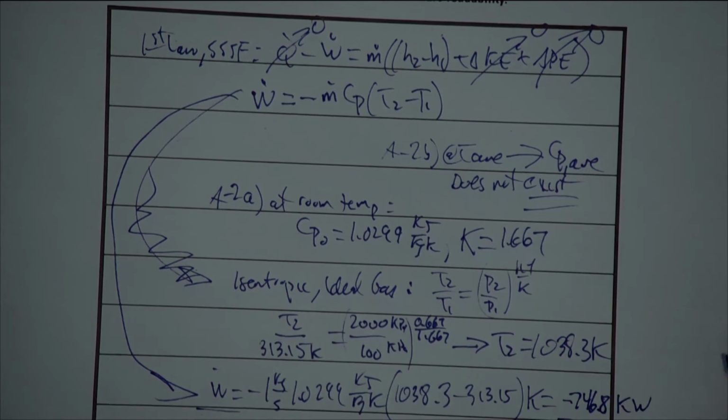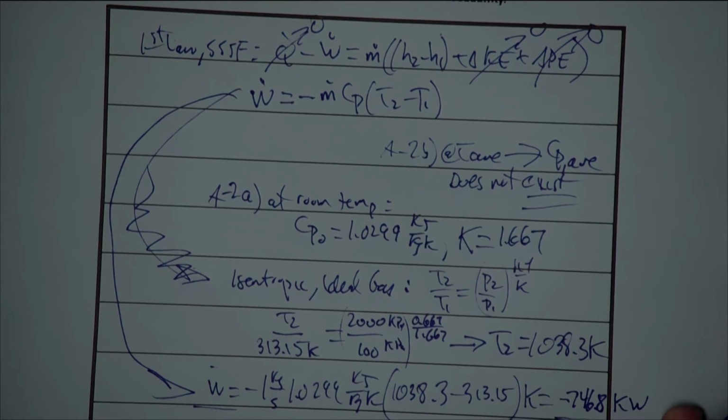And the fact that it's a negative means that power is required, right? Of course it's required, right? The compressor is taking energy from a motor and transferring it to a fluid. It's causing the fluid to move. It's greatly increasing its pressure and temperature. So we would definitely expect a negative sign, and that's what we get.